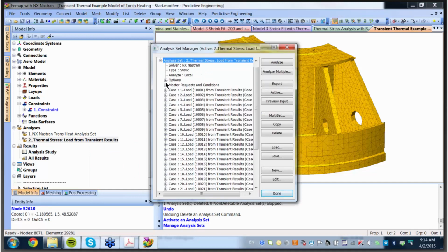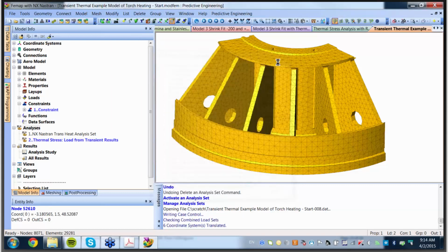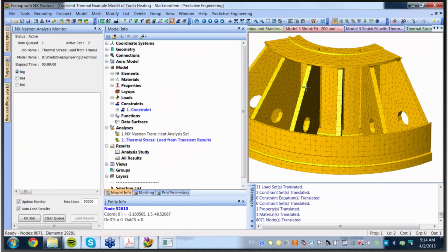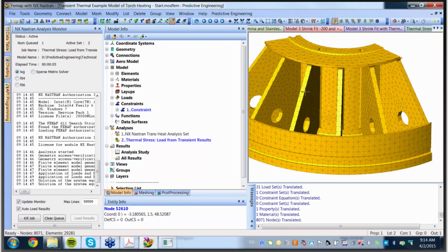Now the Nastran folks know exactly why you want one constraint set. Because you only decompose the matrix once. You first arm it up, calculate all the stiffness terms, apply your constraint set, and then to generate your stress results, you're just applying different loads. And this is very old school. So now when you analyze it, it's only decomposing once, and then it's just boom, boom, boom, boom, boom, generating results from that. Look how fast it goes.